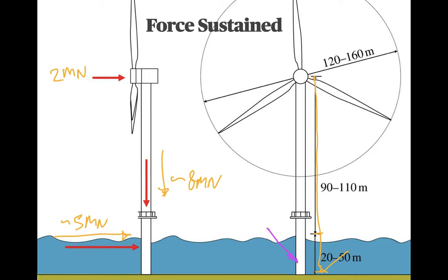And those three things are basically the soil, which can change from spot to spot, the design of the anchor, of which there are a number of very varied designs and not so much agreement about which ones are better, and then, of course, the load that the structure puts on the anchor is also key.